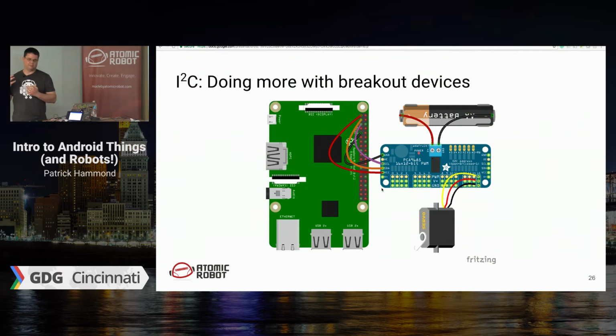So a servo is like a little motor that knows how to listen to these clicks. If your clicks are like 1.5 milliseconds, it can translate that into a physical angle. If you're clicking for 2.5 milliseconds, it can translate that into another physical angle. And as you vary that, things go back and forth. We'll look at some more code for this in just a second, in different ways, but that's what's going on. And I've got a demo of that over here, and we'll look at it here.